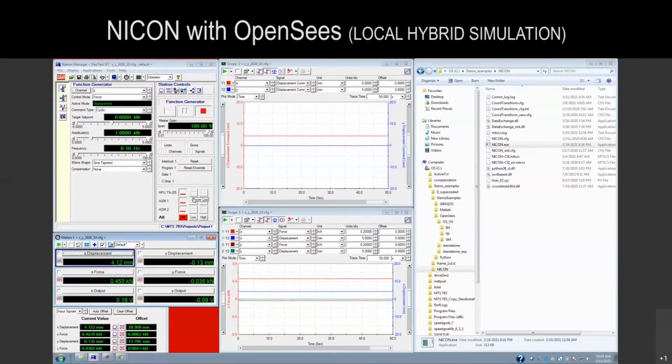Now I'm going to just start hydraulics, and then turn the HSM to high. I'm going to bring the actuators back to the zero load position, just to make the initial condition right. And there is some offset, so I'm going to auto offset that. So now basically the actuator is back at zero load and zero displacement. So the physical test is ready.